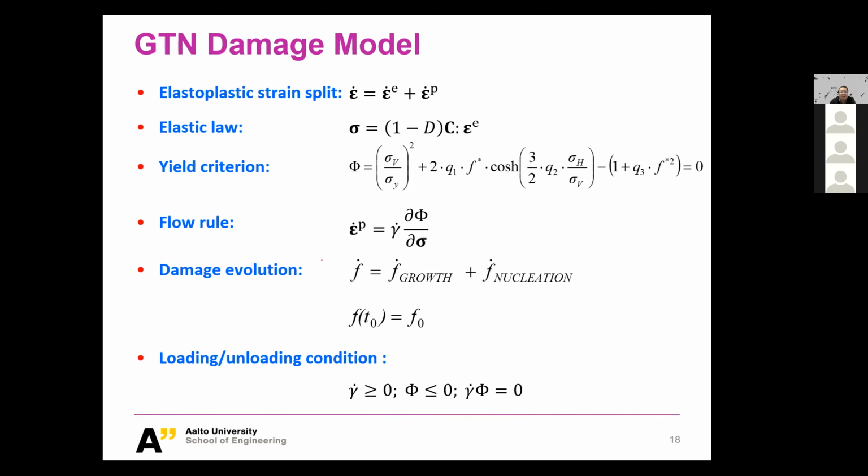But during your exercise, we will show you a rather simpler model, the so-called GTN model. The GTN model is the second important category of ductile fracture modeling. It relies on the idea of measuring ductile fracture via the voids. The main concept here is the so-called void volume fraction. They use the number or volume of voids as a measure of damage. This is very direct.